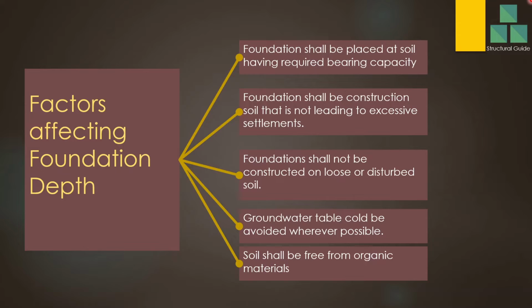Depth should be determined beyond those soil layers because if you have roots under the foundations, with time they may deteriorate. With the deterioration, cavities will be created under the foundations. If you have a significant amount of roots, there will be a big issue. The foundation may settle due to this deterioration.